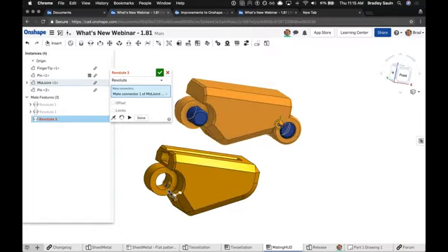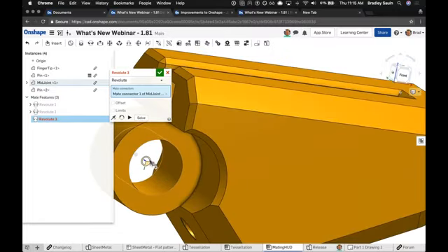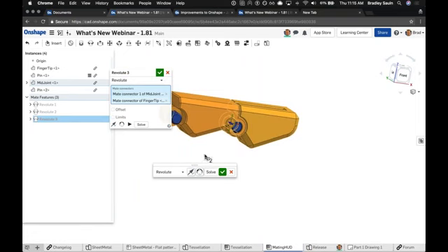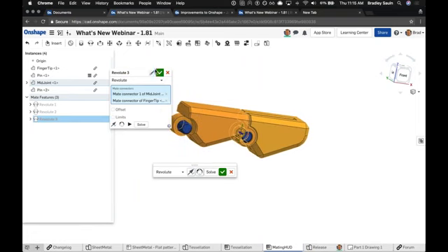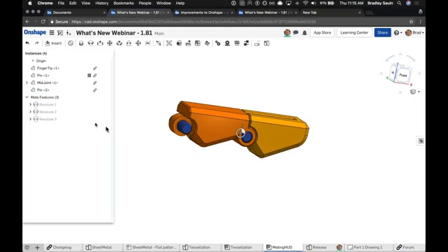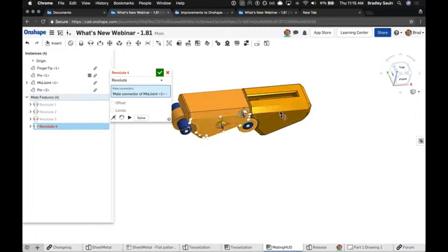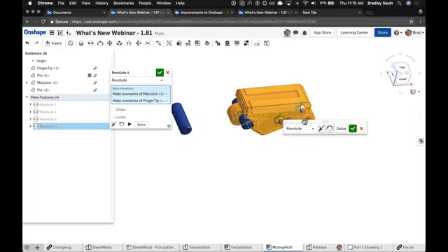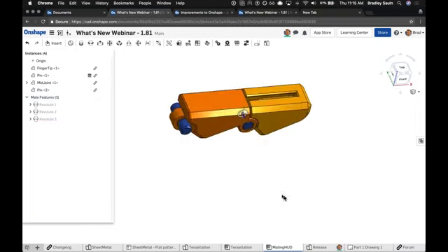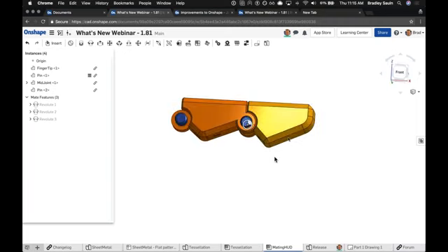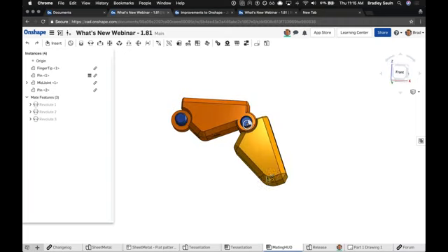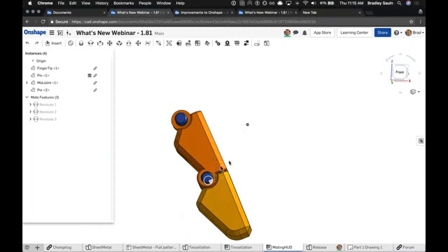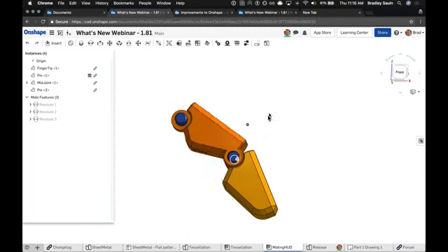and start to add all these components together. So again, just some nice quick workflow improvements. I can choose then to hit the green checkbox of the main mate dialog to complete this command. If I'm still within it, let's just try to do something dumb to get that to reappear. I can always exit out at the end to also complete that action. And then we'll see now everything is fully mated around, fully controlled here to my design. Very, very quickly, just an attempt to improve the workflow for people.